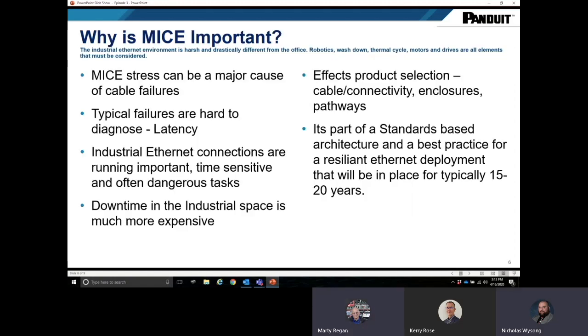Thank you, Nick. As we've mentioned, industrial environments are harsh and very different from the enterprise area. Exposure to high temperatures and thermal cycling, high pressure spray, movement, and vibration are all a major stressor to the cable. The failures associated can be minimized by applying M.I.C.E to your network deployment strategy. The majority of failures are hard to pinpoint, intermittent, and create delay in the time it takes for a signal to pass to a device.